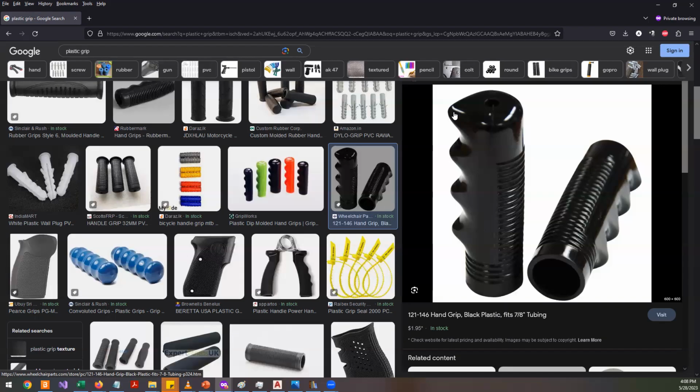So if there is a shape, or a part of a shape, a part of the body, where the cross section changes, and you can't model it with the extrude, sweep, or revolve command, then this will be your trump card. If nothing else works, then loft will work. Simple as that. All right, let's see how you can use this command in an application.